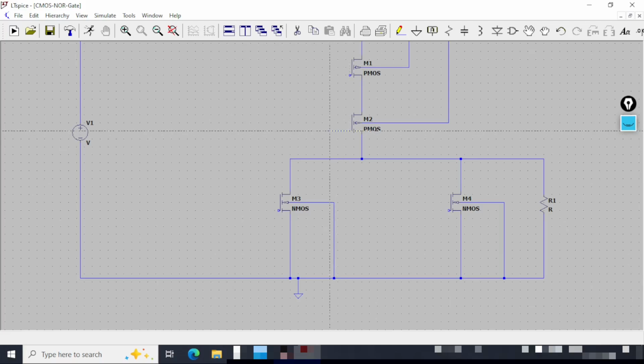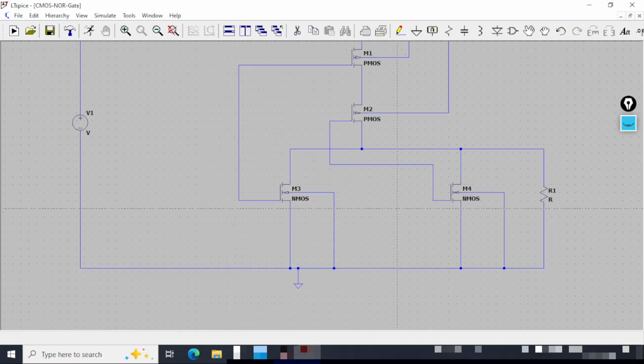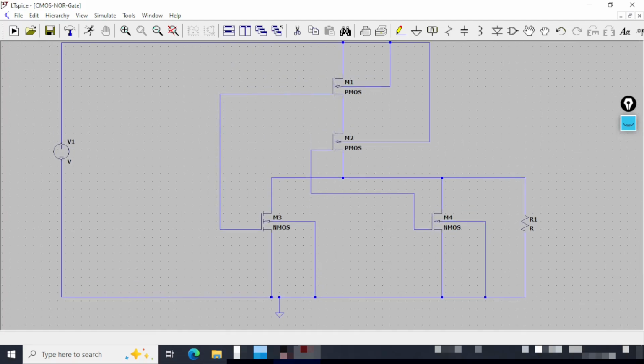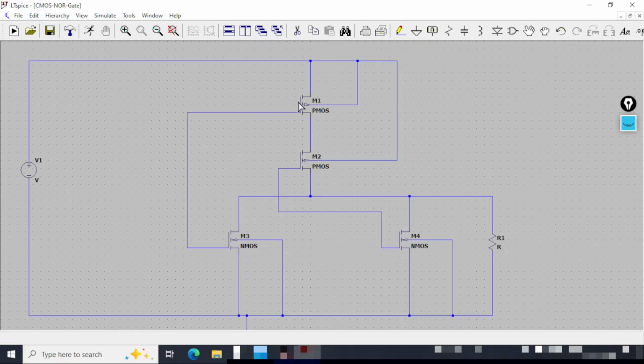This point I connect, click, come down, go rightwards, click here, come down, and then I connect. I'll click here, come up to this point, go up to this point, move rightwards and connect with this point. Now, I think the interconnections of this circuitry are done. We are yet to connect two voltage sources. All the MOSFET nodes are connected.